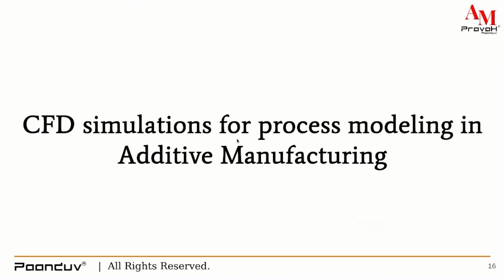Now, second part, once we have achieved a good packing density of these particles onto the substrate, the next part is you shine the laser on top of it and multi-physics phenomena start happening. And for this, CFD simulation is very important to capture this crucial information from the LPBF process.